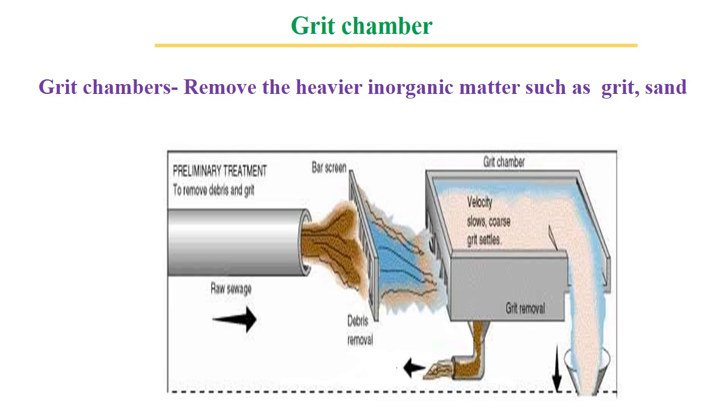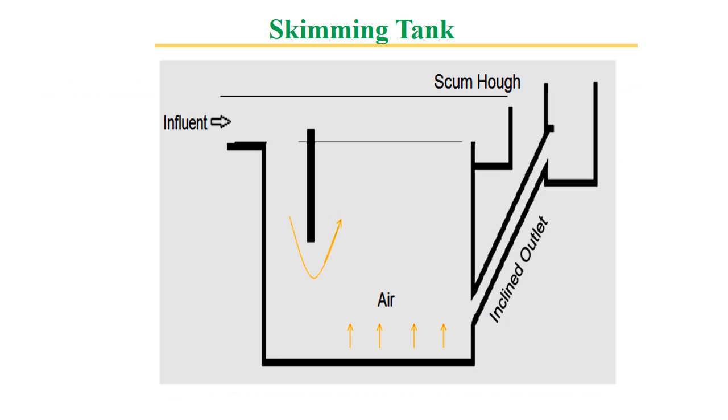So this is another step for primary or mechanical treatment, which is done through a skimming tank. Here the effluent comes and falls into a big tank or pond-like structure, in which at the bottom there is an air pump which makes things float to the surface, all big things along with scum, and that is separated through a mechanical skimming mechanism. That helps in removing any remaining big things in the effluent.